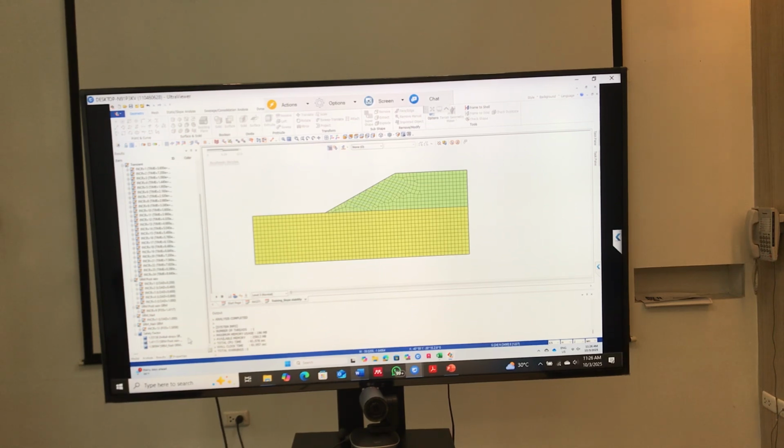So these are the results. You can see the factor of safety. Initially, the factor of safety was 1.5. When it rained, it reduced to 1.4. Then when we installed nails, it increased to 1.58. These are the values which you can use if you are predicting the stability of the slope after installing the nail. If you want, you can also change the location of the nail, or change the length and see the variation. So that's about factor of safety.